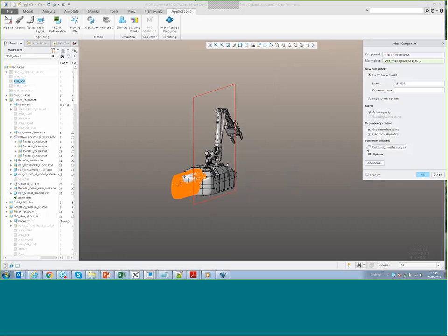So you imagine how many components are symmetrical. Cars, bikes, this robot, loads of things have symmetry on them. Now, ordinarily, if you had a car, and I've done a lot of work with car design in the past with the likes of Volkswagen, Audi, etc., you tend to design one part of the car. And then when you come to mirror it, you'll have wheel front, wheel back on the left, and when you mirror it, you end up with wheel front right and wheel back right. You end up with 4 unique components, which is a bit crazy because in actuality, they are the same part.